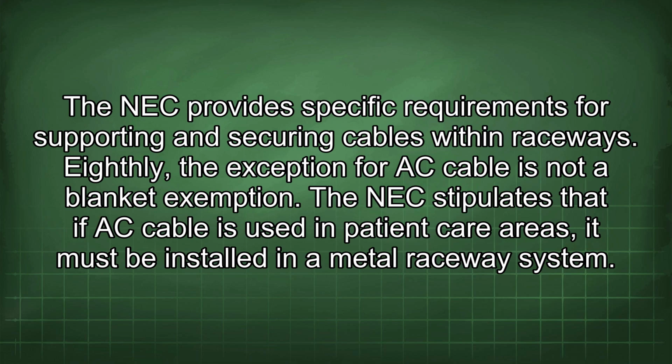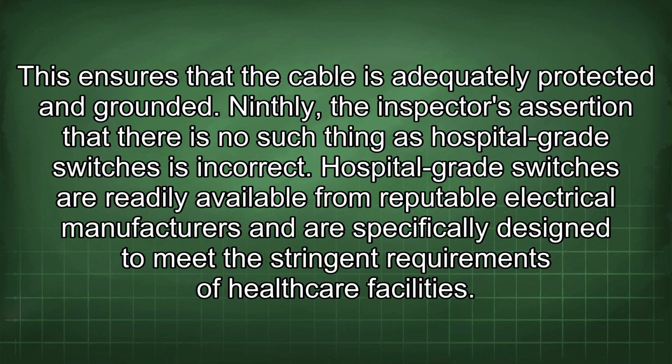Eighthly, the exception for AC cable is not a blanket exemption. The NEC stipulates that if AC cable is used in patient care areas, it must be installed in a metal raceway system. This ensures that the cable is adequately protected and grounded. Ninthly, the inspector's assertion that there is no such thing as hospital-grade switches is incorrect.